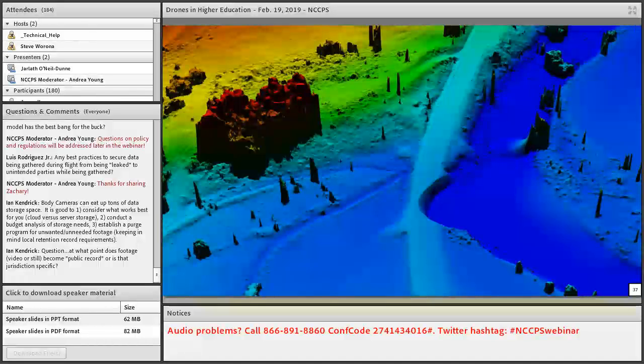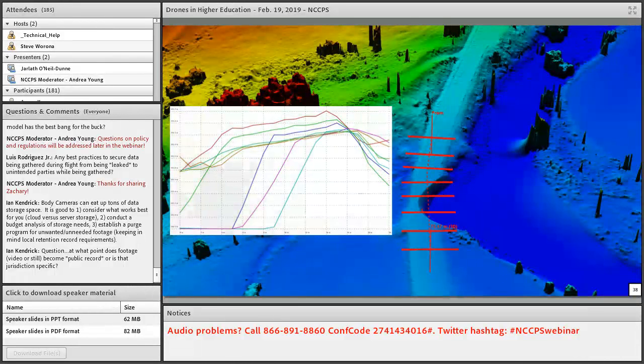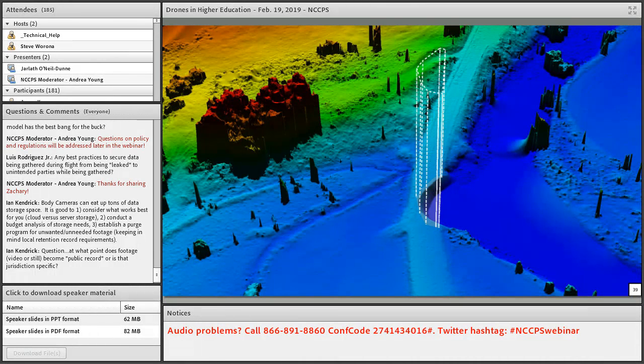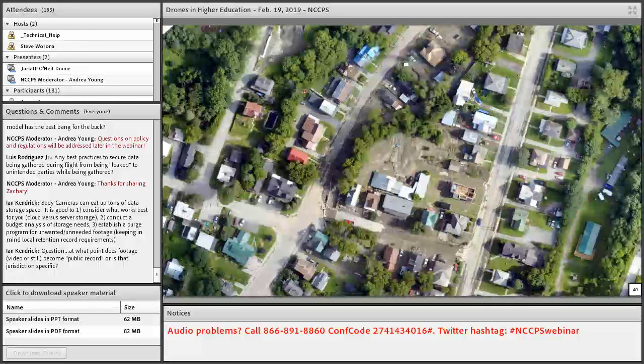And then if we were to, say, suffer a catastrophic incident on that road, say a flood that washes out a portion of the road, we can then use these 3D data within geospatial software packages to make detailed measurements of that washed out area and accurately compute the volume that we need to replace that road. So if we want to get fill in there, rather than sending a surveyor out to survey it, or maybe it's an area that's inaccessible, drone technology and the 3D models coming from it allow us to do these advanced analytics. So don't think of drones as just photos and videos.